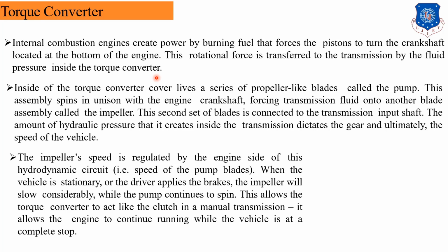This force is transmitted to the fluid, and this is the fluid pressure inside the torque converter. So a torque converter is a device which increases the torque of the vehicle with the help of fluid pressure. Inside the torque converter cover there is a series of propeller-like blades called a pump.